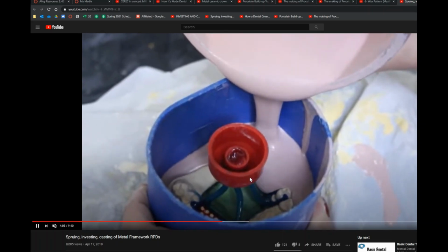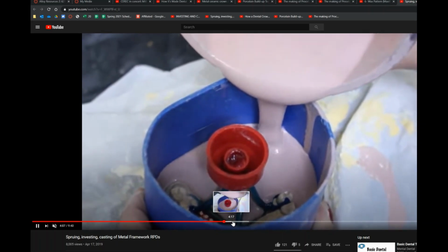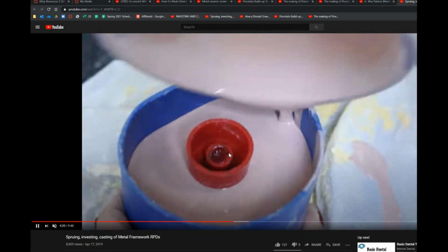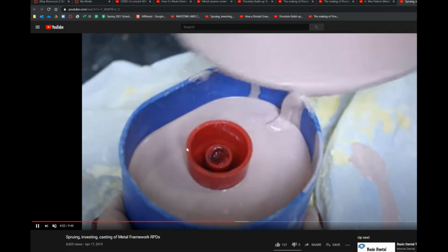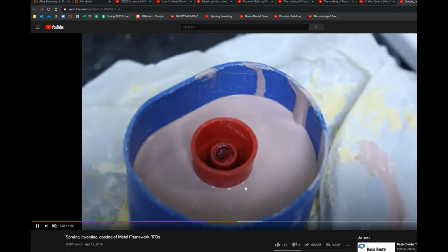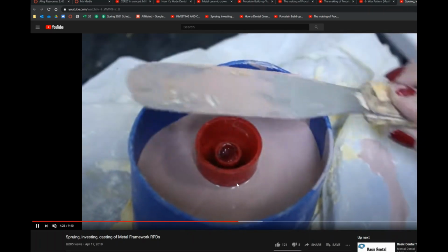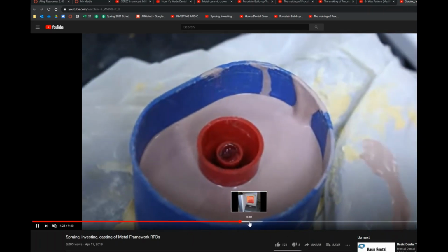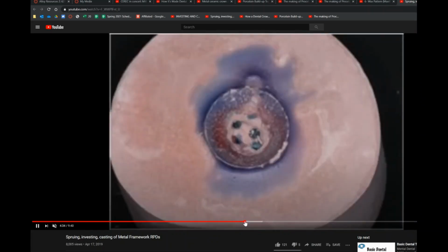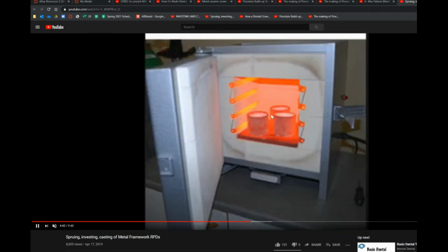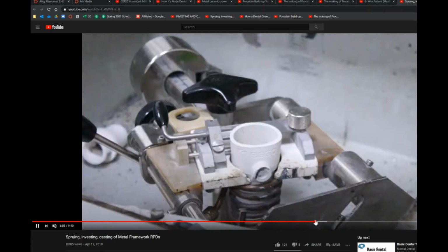So this is wax, and we're just pouring the wax on. Now we have that only, that's the only place that is left. So that's the place that will be the guide for the metal to actually fill into place. So this is where we put the wax in a furnace, and that is with high temperatures, and this would evaporate all of the wax that is inside and will leave us with an empty space.